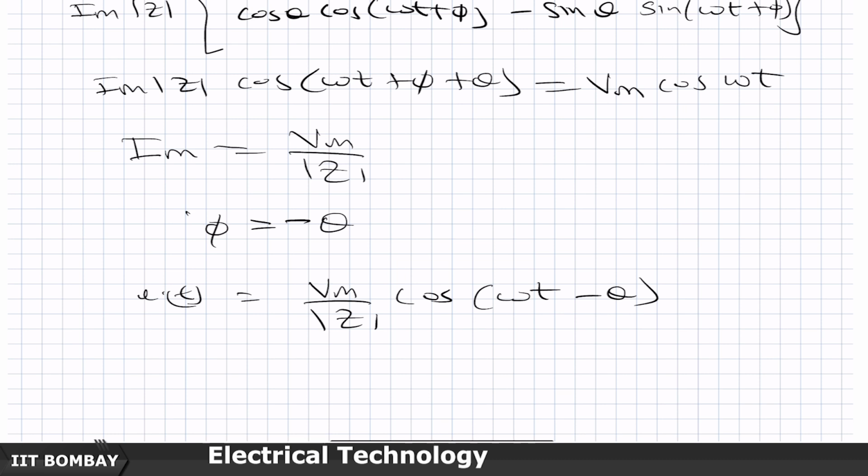So suppose again the theta turns out to be 30 degrees. The ratio between omega L and R is such that tan of theta is tan 30 degrees. So sin 30 degrees is half divided by cos 30 degrees, which is root 3 by 2. So this is 1 by root 3. All we are saying is the ratio of omega L by R is of the order of 1 is to root 3.